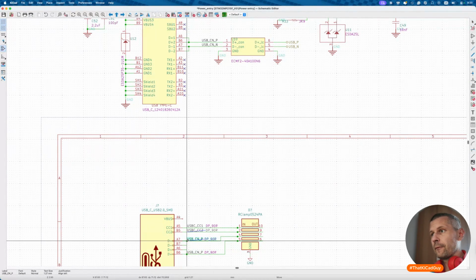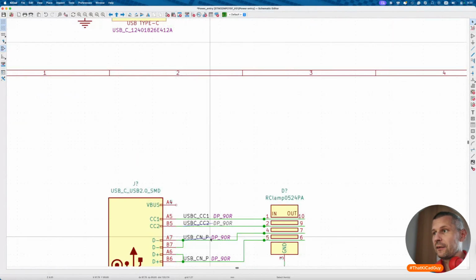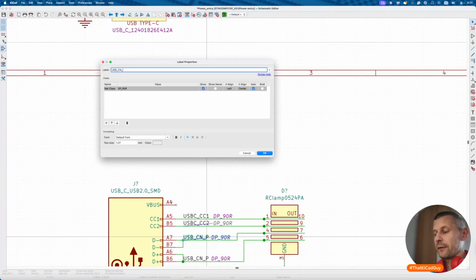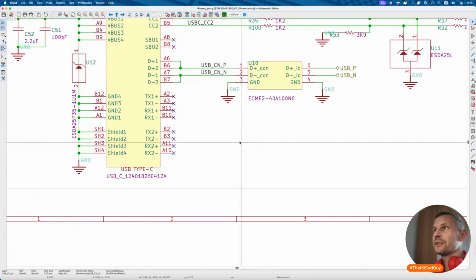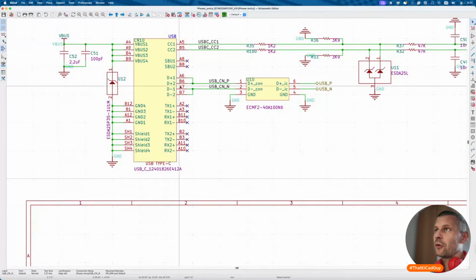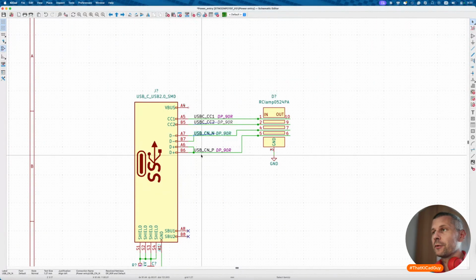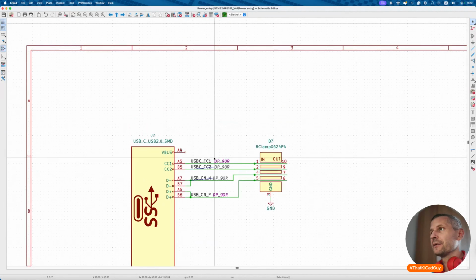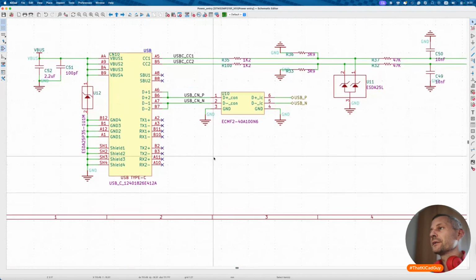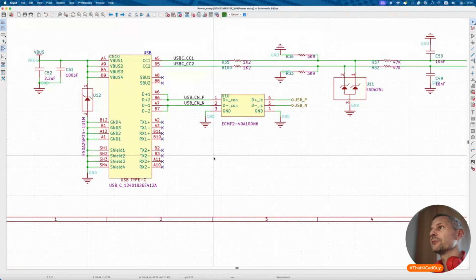Yeah, always be careful when assigning this minus plus signals, because as you can see, this connector has plus on the top and my connector has plus on the bottom, so it's easy to switch them, and the result is usually catastrophic.